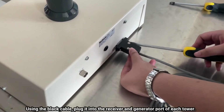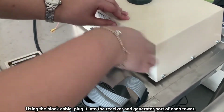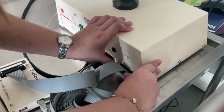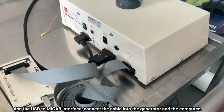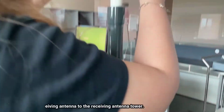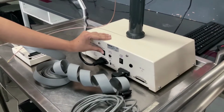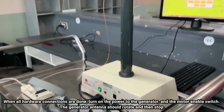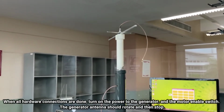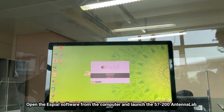Using the black cable, plug it into the receiver and generator port of each tower. Using USB, connect the cable into the generator and the computer. And then attach the receiving antenna to the receiving antenna tower. When all hardware connections are done, turn on the power to the generator and the motor enable switch. The generator antenna should move and then stop.